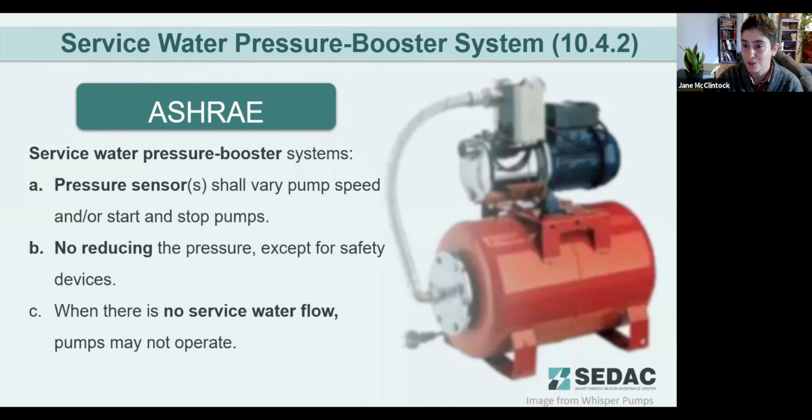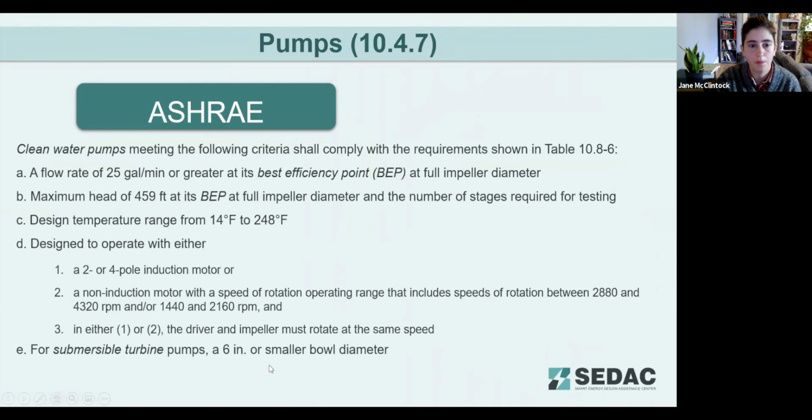In my opinion, if you're designing a service water pressure boosting system and you're not sure what to do, please reference ASHRAE, even if you're not using it for compliance, because these are really good ways to reduce energy use. They make sure that when the water is not being used, the pumps are not operating and maintaining pressure in an unoccupied building, and you're not reducing that pressure after creating it, except for safety reasons. And then controls to start and stop the pumps.